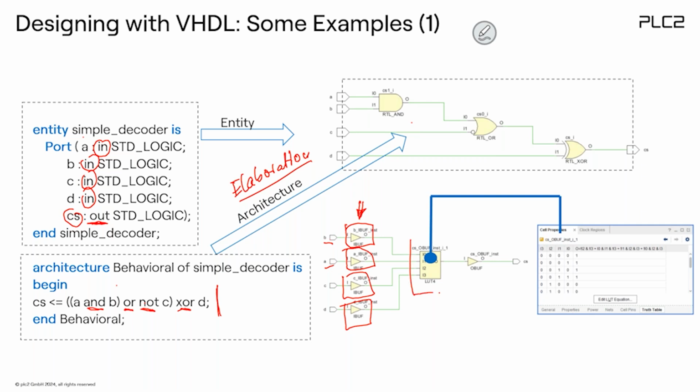Then you will see here actually the lookup table, and from the first part, maybe you remember that the lookup table is exactly the location where the combinatorial logic is implemented. So it's actually a lookup table implementing exactly this function. You see the contents of this lookup table is nothing else than this truth table.